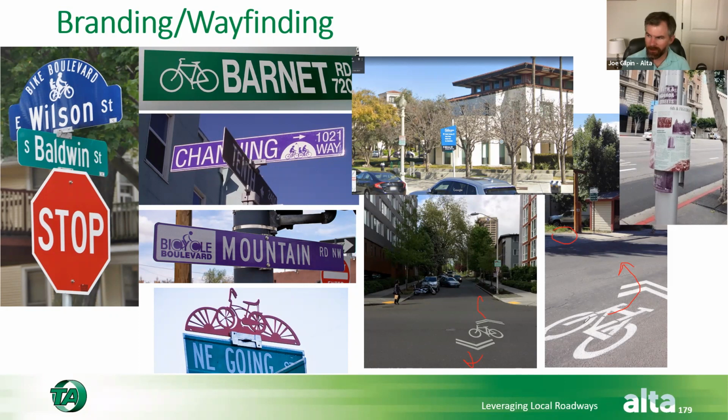This one would technically not be looked upon favorably by the FHWA because they think that this is a lane positioning device, and if you turn it into a wayfinding device, that is two things at the same time, and smoke will start pouring out of your ears, and galactic paradoxes will occur and all kinds of things. But in reality, people get it. The FHWA has experimented with wayfinding markings and hasn't found as good legibility as just using the shared lane markings for that. So I'm in full support of using the markings to help overcome changes in direction and other types of issues like that.